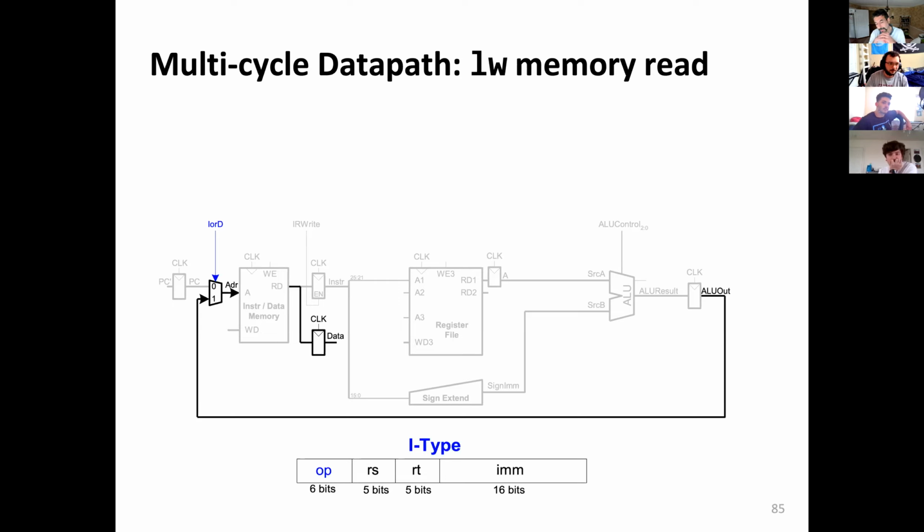But why didn't we have this in single cycle? In single cycle, we didn't need it because we had our own separate set of hardware to take into account those tasks. We had separate ALUs and separate memory read and write. Or let me ask, what would go wrong if we store this in the register file? If we stored them in a register file, there's a chance that we would accidentally overwrite that register file and lose the data we were working with.